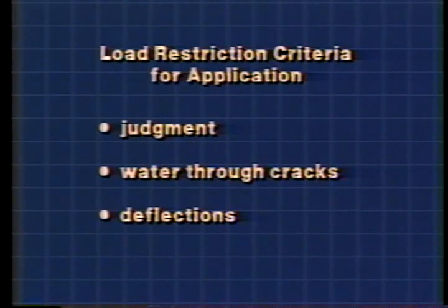The basis for starting a load restriction varies from judging the presence of water coming through cracks and joints to the use of deflection measurements. The majority of the agencies rely on the judgment and experience of field personnel.